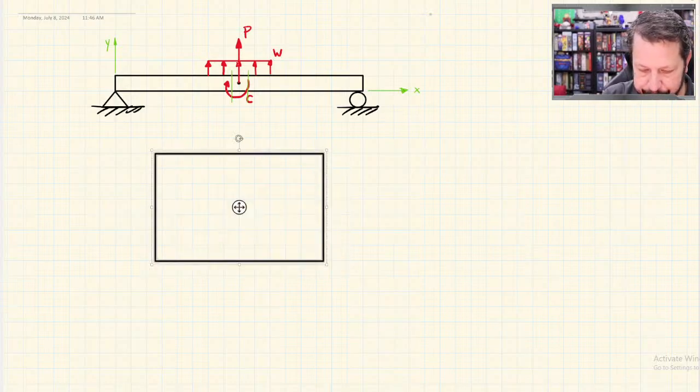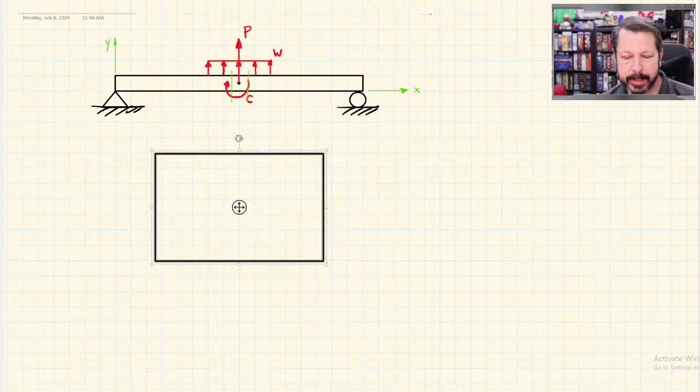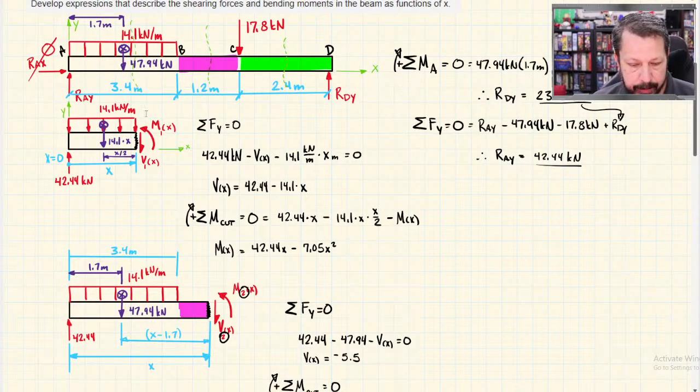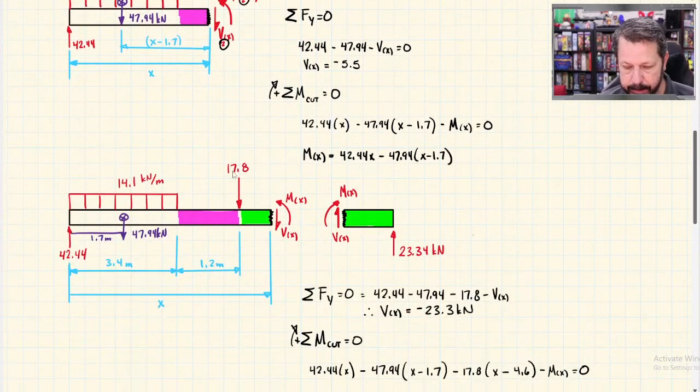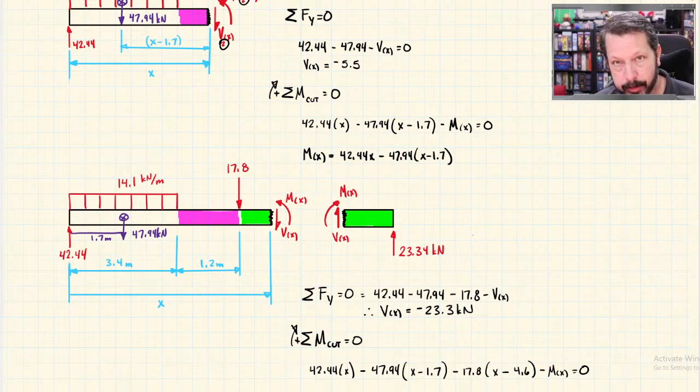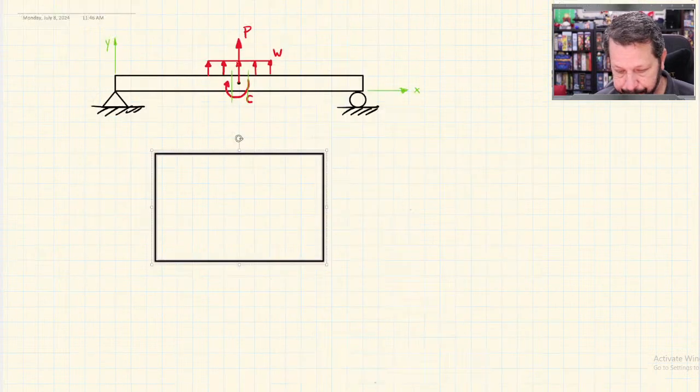So we'll try and line it up there. This is our enlarged version of that tiny little section that we just drew. We've already decided the sign convention for internal shear and bending. I think this one shows both sides, where we've already decided which way is positive. So I'm going to use this same convention on our little section we're drawing here.